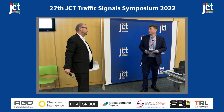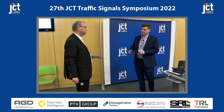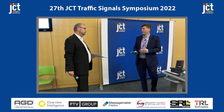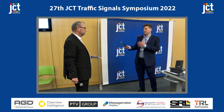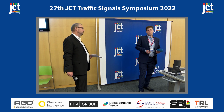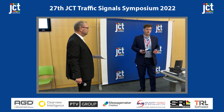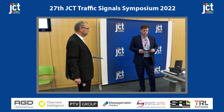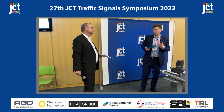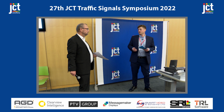Yeah, obviously with the design we try and keep a level difference as well, so we try and let cyclists know where their lane is and they can use that lane and go to where they go to. We put crossings on what we feel are desire lines so that pedestrians wouldn't feel the need to hop into the cycle track. We've also got some data being collected at the minute and drone footage on the first drawing that I showed you, so that's currently live. The findings haven't been published just yet, but that's looking at the cycle and pedestrian interaction, the movements, and any compliance issues. So once we've got that feedback, we'll be able to see how well it's working.